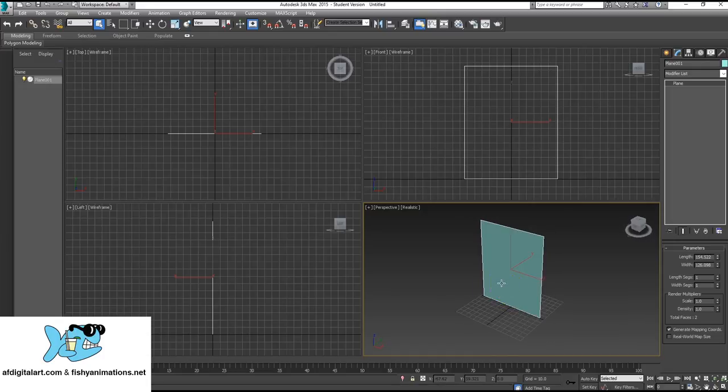Now let's learn about the move tools. Up top, you're going to notice I got select and move, rotate, and scale. These keys are also found on your keyboard. Move and select is actually W. And you're going to see when I select W, I have what's called a gizmo, and it's a controller. It has your X, Y, and Z axis.